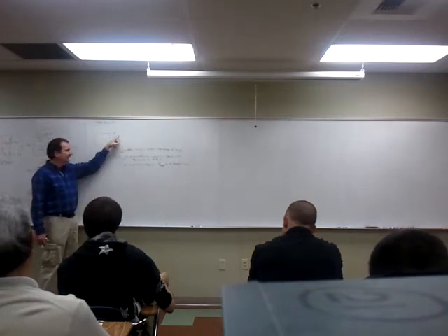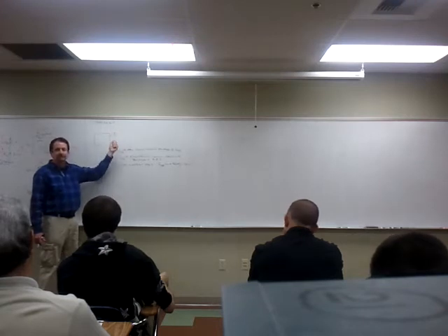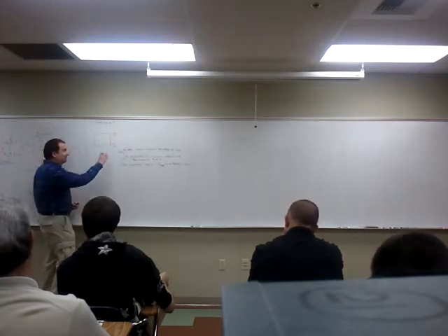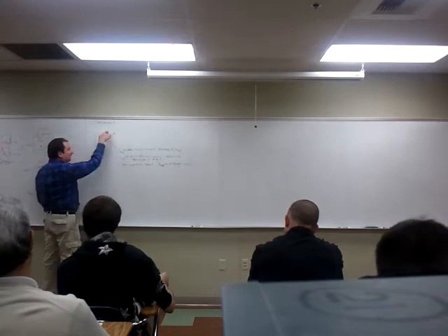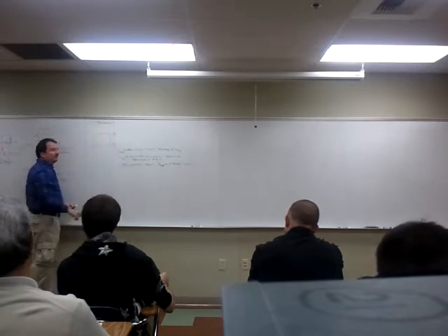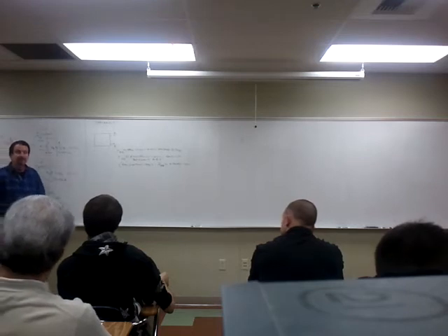In other words, you measure the voltage before putting a variable resistor on, then you adjust it for half the voltage. The only way that would happen is if the voltage here was the same as the voltage across all the internal components in that box.